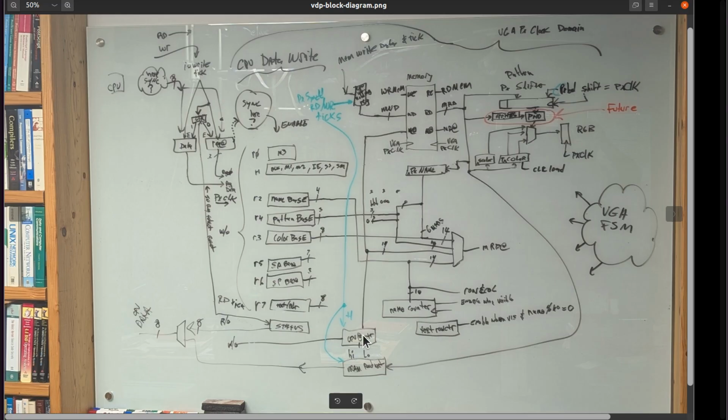Now, we'll take a look at the VDP doc in a second, just to recap how this whole thing works. The short of it is the CPU doesn't just simply throw over an address and say, here, I want to read data from that address, and then pow, it gets it back. It's not a regular RAM like the main memory of the Z80 style bus, because the address used comes from a counter down here that the CPU can set, in very much the same protocol that it uses to write values into these control and configuration registers that we already talked about.